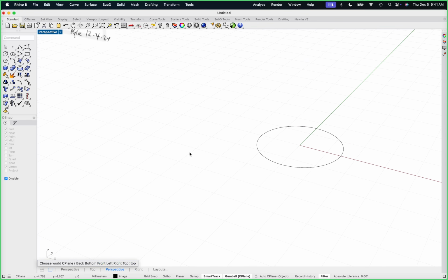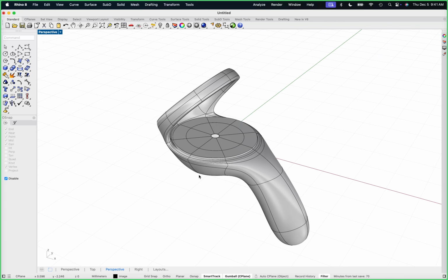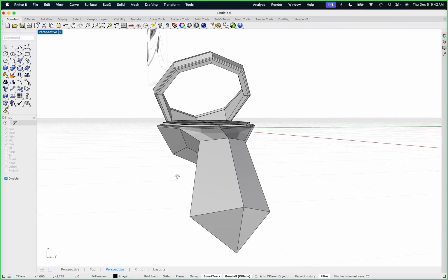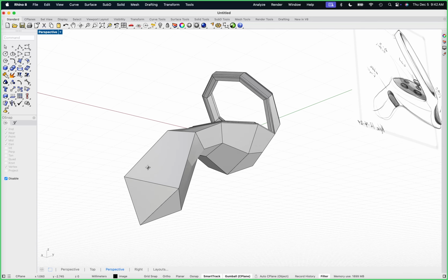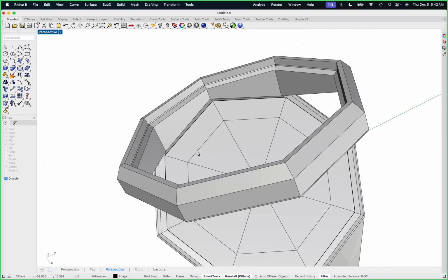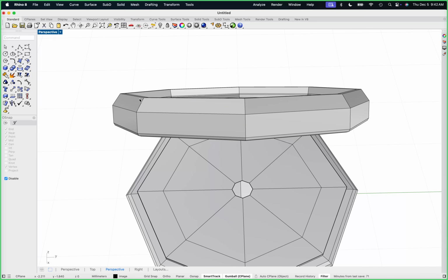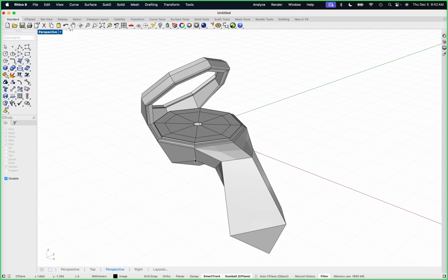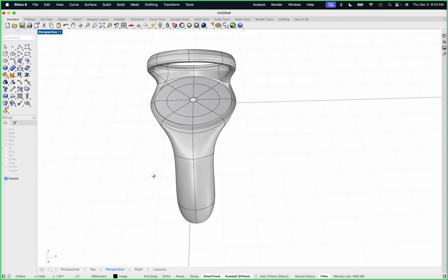And 90% of the time, when I see a problem with a SubD model, or the customer sends a SubD model, it's because they've got too much stuff. These models should be very simple and very easy to understand when you go into box mode, and they should all be super organized. If you're sighting down a line and your isoparams are super up and down, if points are crossed, if things are spiking off into space, if anything like that's going on, you probably did your modeling in smooth mode instead of box mode.